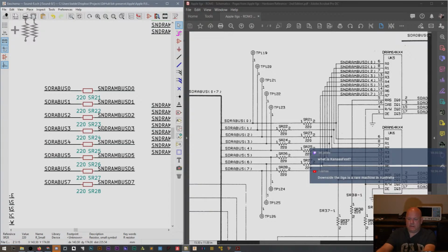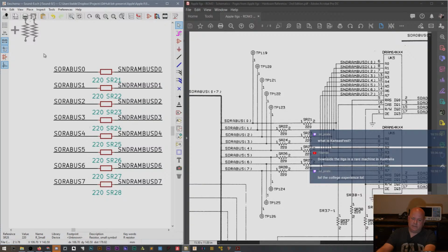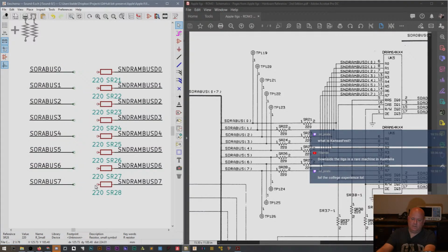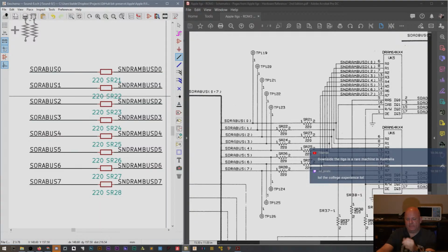Okay. So that gets all the test points. Darn it. Oh, this just gets messier and messier. Because to get test points out of escape all of these, I have to do something like this. So by the way, I'm hovering over the square and hitting G to extend those lines. G is like such magic. So they have 1, 2, 3, 4, 5 test points.